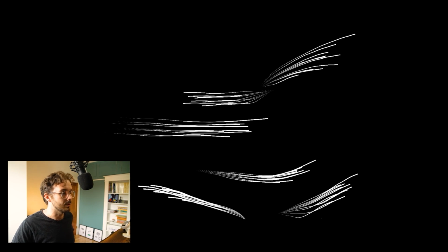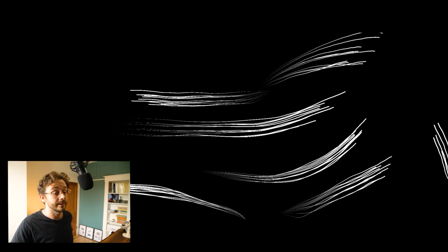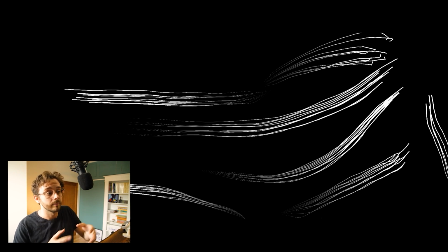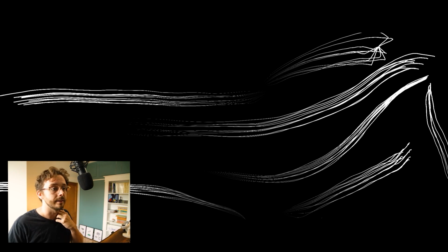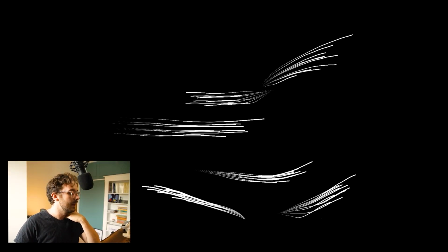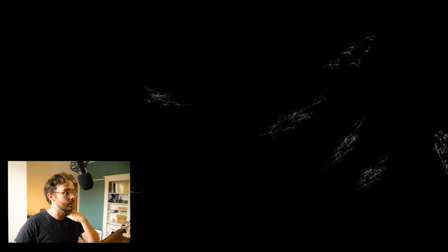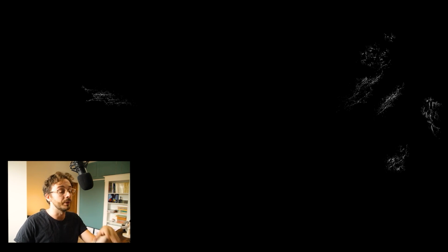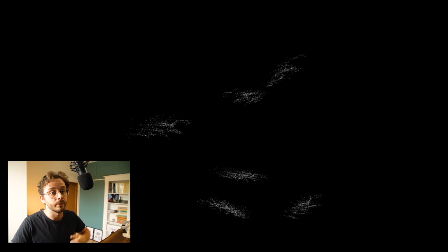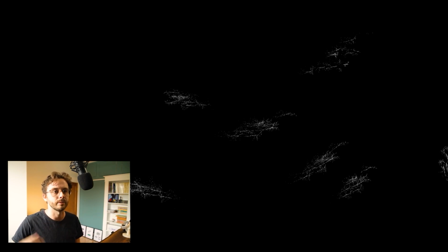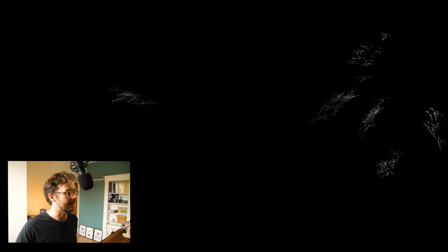Then after that, what we can do is what I showed you right before. We can do a quick tracer out of that and have all those lines being created out of the parrot, so it's gonna help me for one transition inside of the project itself. We then have a super simple and effective X-Particles simulation in which we just use the feather to create particles, and we just simulate that for all of the systems. We are using that to create some kind of smoke effect at the end, honestly.